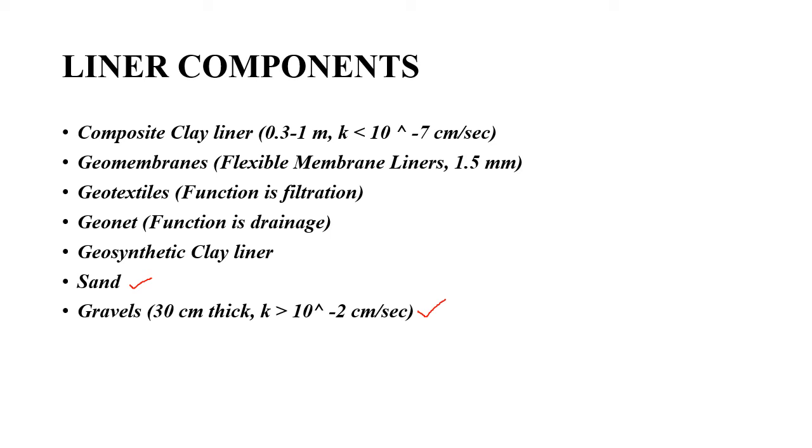That defect can be overcome by the use of equivalent geosynthetic materials which can serve the function of filtration and drainage. So you can use geotextiles instead of sand. It is a polymeric material.